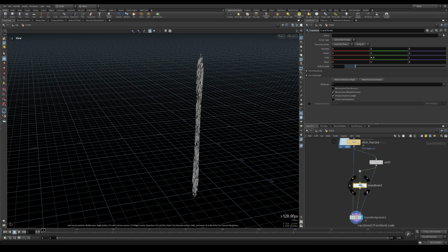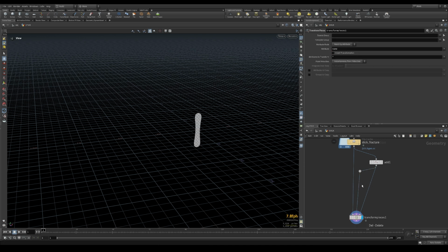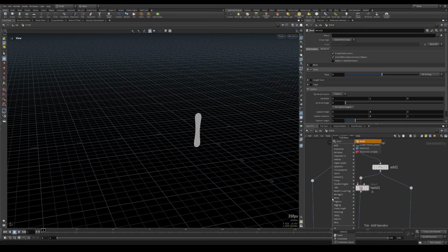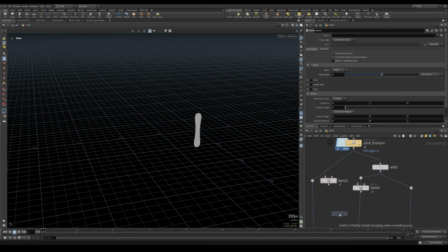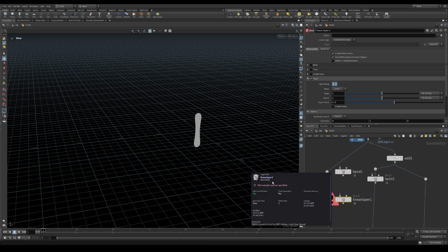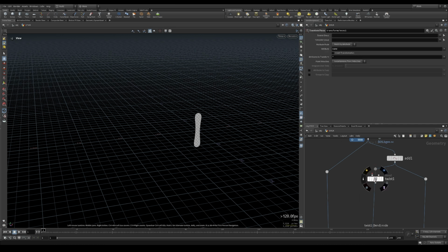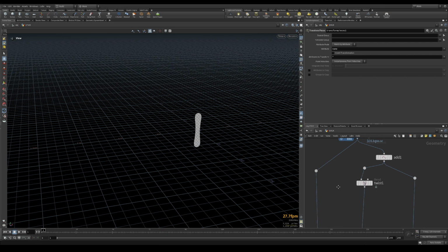So let's delete this transform. We will apply some scaling, but not with a transform node. And maybe let's rearrange things to make some room. And if you press Alt and click and drag on a chain, you will create this reroute node, which is very handy. So first thing first, let's take a twist node, which, by the way, if you take a bend, a twist, or a taper, as many nodes in Houdini, you realize that they are the same node, they are just preset in a certain way. So doesn't matter if you take one of those, it's always the same node.